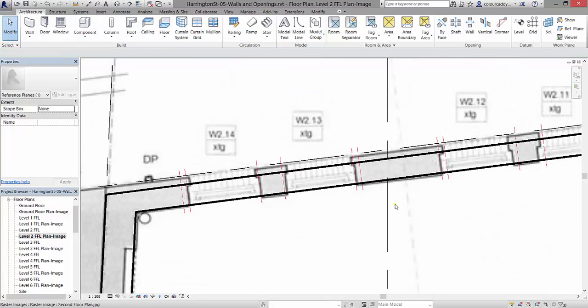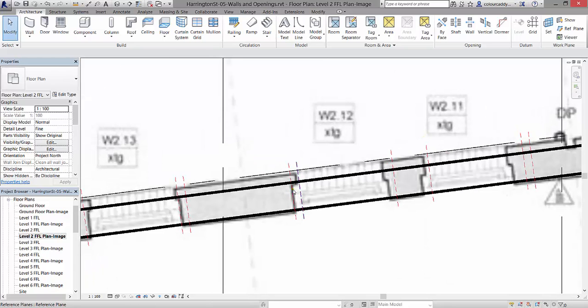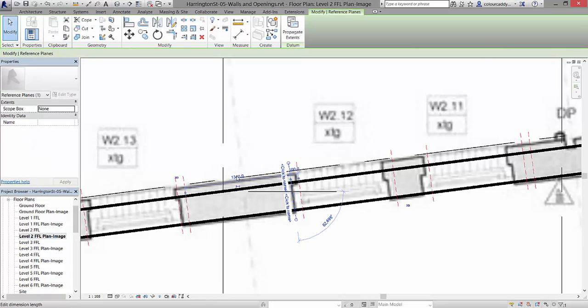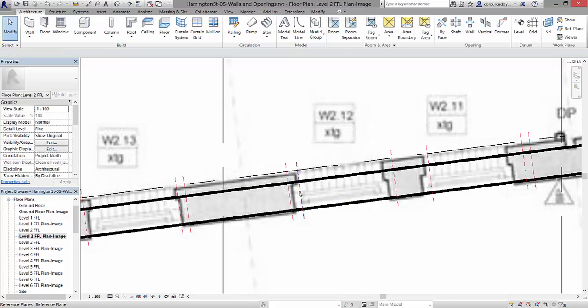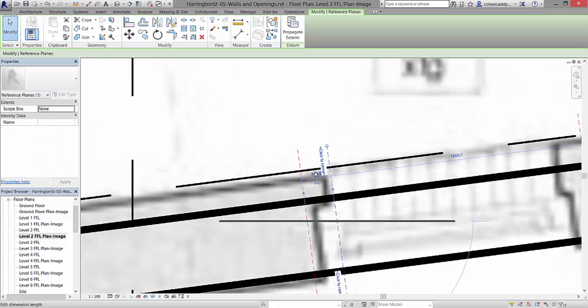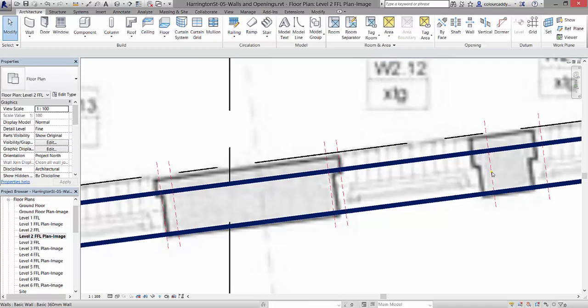Once we have two bays set out, the rest should just follow on automatically. Okay, so this next one, I might make 1300. I think it just does need to come a bit back to the left if it can. Even though it's not in line with the drawing again. Remember, the drawing's out, we've just got to try and work around that. So here we go, 100 for that. And the opening should then be 1200.